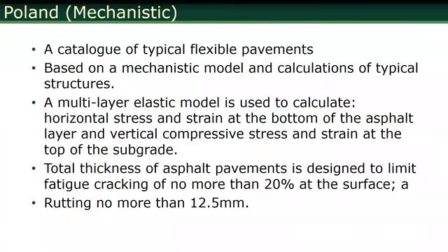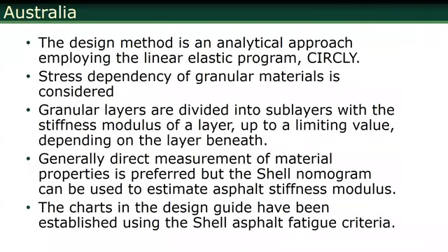A multi-layered elastic model is used to calculate the horizontal stresses and strains at the bottom of the asphalt layer and vertical compressive stresses and strains at the top of the subgrade. So total thickness of the asphalt pavement design is designed to limit fatigue cracking to not more than 20% at the surface and rutting to not more than about ½ an inch or so. So these are the limits, and they've run a whole bunch of analyses and came up with the catalog, and that's how they use it.